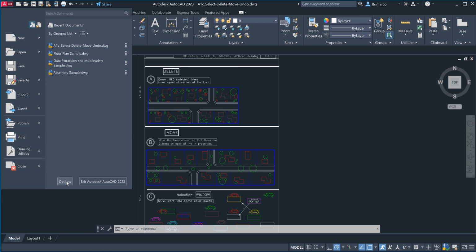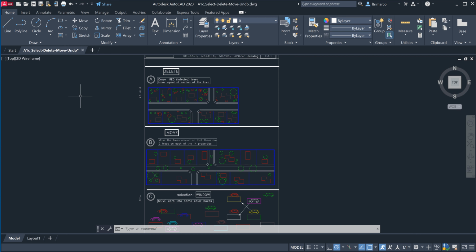So we can get customized, but for the most part, for the next couple weeks, I'm going to pretty much stay standard in AutoCAD. As soon as you open up AutoCAD, you will always be by default highlighted on the Home tab. The Home tab, as you can see in the upper left, houses many panels. It's kind of a tabs and panels interface, if you will. The far left is called Draw and Modify, and this is where we're focusing today and next week and the following. We're going to draw some objects, or we're going to modify some objects by moving or copying.